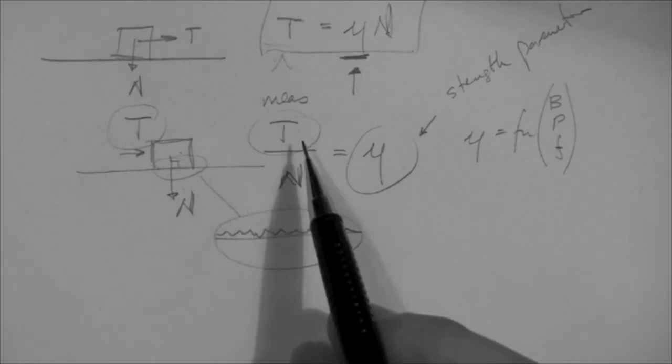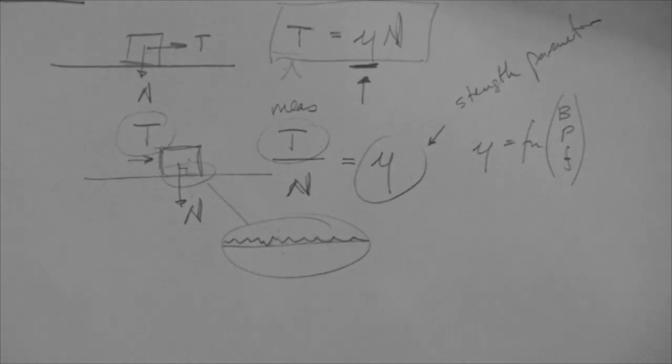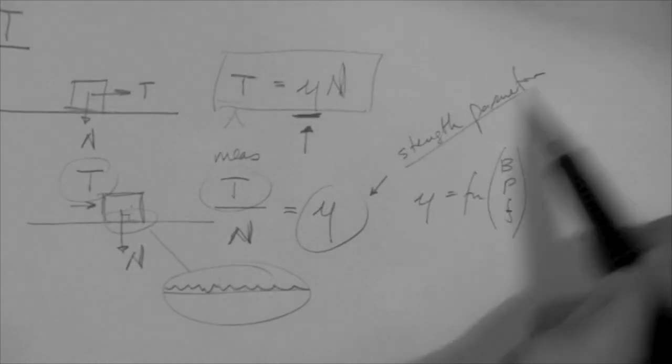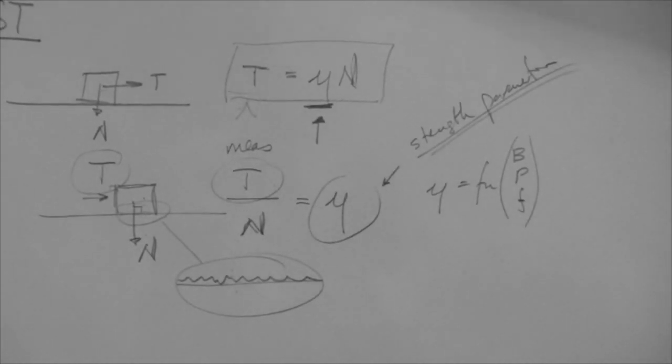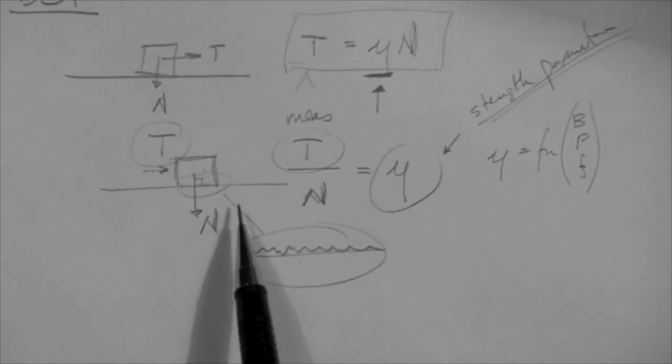We are not in search of the strength. We measure the strength because we take the specimen to failure. Therefore, we can extract the strength just by measuring it. And then we solve for what are, in our case, two strength parameters. Okay? And this is what you would be, let's say, paid for if you were to run lab tests on a soil, if you had a firm that does lab testing. Okay? So we're going to replicate this in the lab for soil. How do we do that?